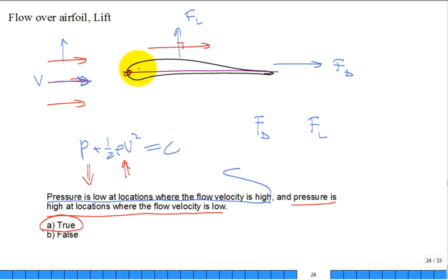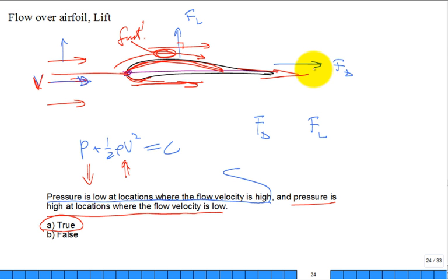All right. So what do you want to do with an airfoil? One way to view the behavior of an airfoil is to have more of a bump on the top side. What do you mean? Displace the fluid more on the top side such that when it splits this flow, it's going to have to go over and go faster to get around it at the top. So make the flow on the top fast. What does that do? Makes the pressure low. And the low pressure is going to help it lift. What about on the bottom side? Well, on the bottom side, you don't have such a severe bump. Have it where it stays relatively slow or the same speed v, and typically just get it to match back up down in here. Okay? So the purpose of the airfoil, the simple way to explain it, is to get it to go fast at the top to give a good lift.